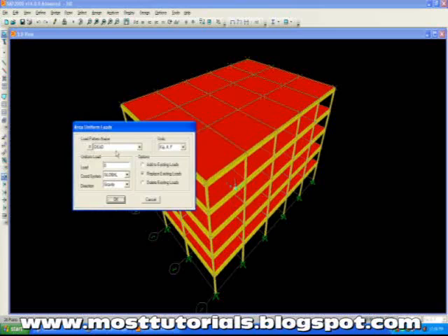When I say selection, I have beam and slab, and I am applying load to area, so load will be applied only to area, not to the frame or beam. Although in selection I have both frame and area, because I am assigning load to area, load will be assigned to area only.